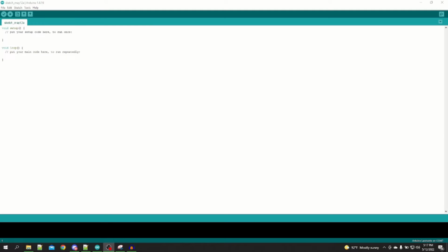And I say as much as I can because another thing happened. I get all the way to the end. I do know that the program worked. However, there was a problem with the LEDs, so the LEDs don't light up. I was able to verify with another set of LEDs that they light up properly. So I know the code works, I know the Arduino works, I just have a problem with the LEDs.